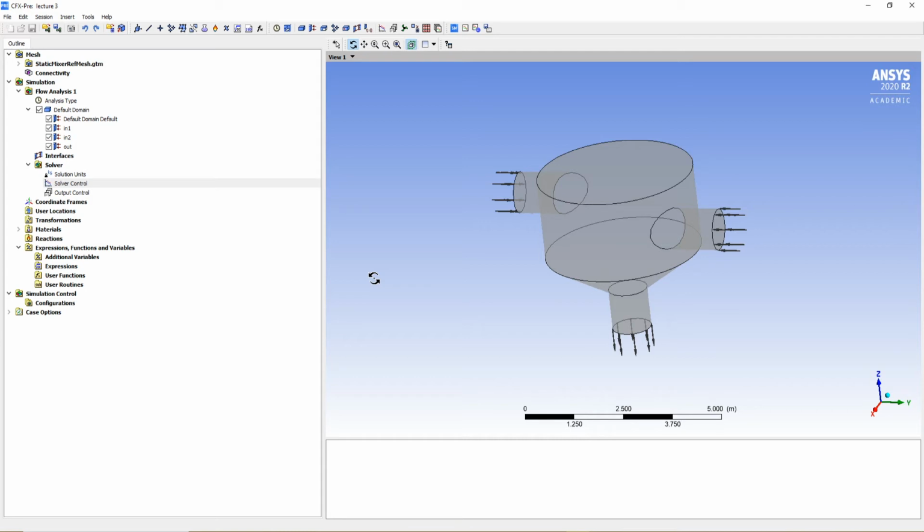What's gonna take time is when you run the simulation and you see that the results are not quite as I expected. Maybe you are comparing it to a physical experiment and your simulation results are not similar to the physical ones. So you need to go back to your setup, or maybe to your geometry, maybe to your mesh, and this process of going back and checking is where it takes time.